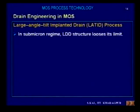They are mentioned here. In the submicron regime, the LDD structure loses its limit because you are creating two drains. One is lightly doped and another is highly doped. If you use two drains, you cannot reduce the drain region to be extremely small.